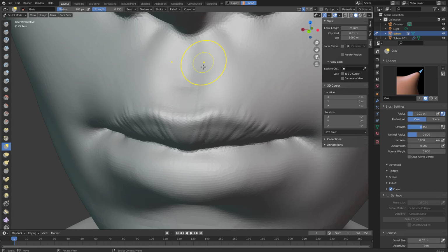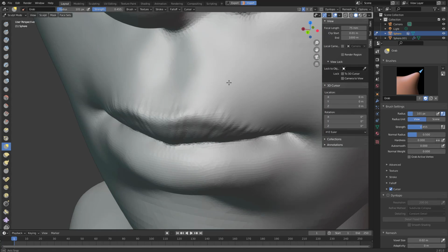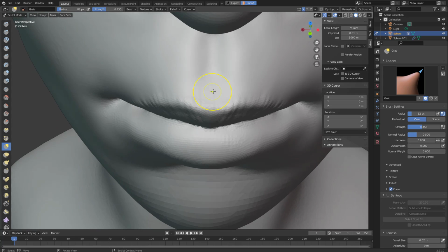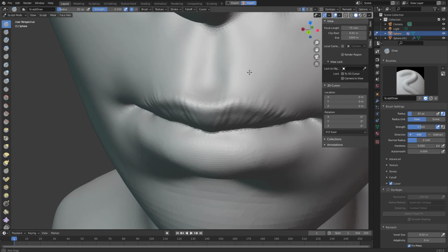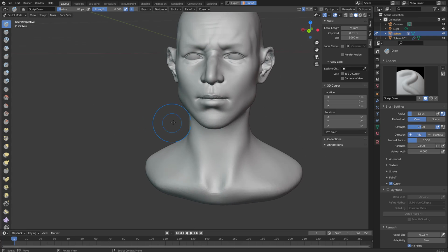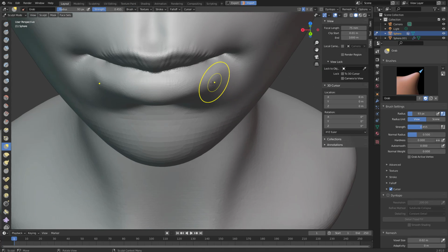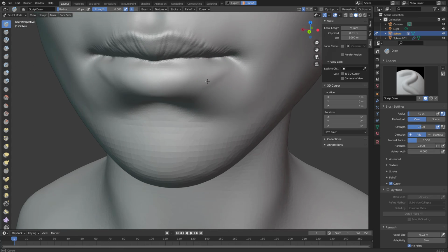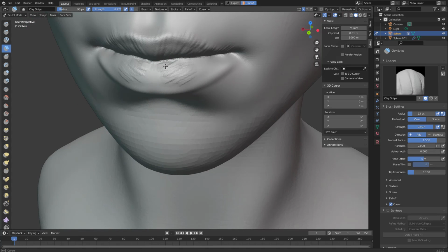You can see before I was trying to do the retopologizing, right, by using Dyna Topo to have more resolution here. I went further than the lip because I know I need to smooth those areas, and the smoothing wouldn't work nicely if the resolution is very different. Okay, that's the upper lip. The lower lip is going to be similar. I guess I can define the ridge here first. I can define some more volume in here.